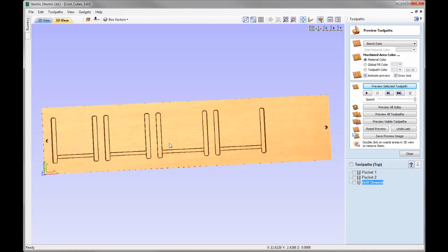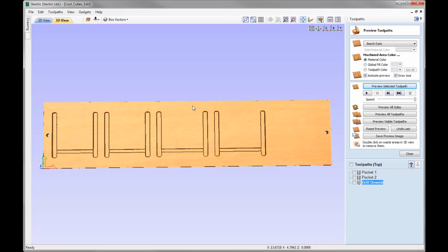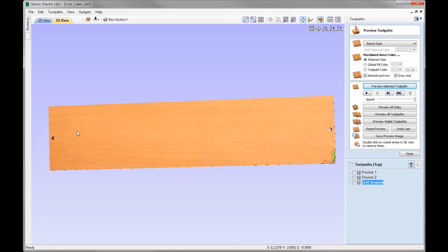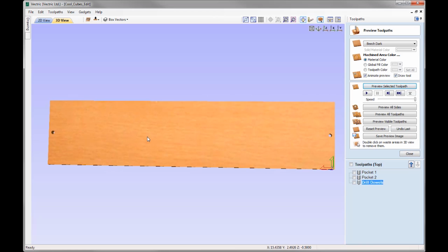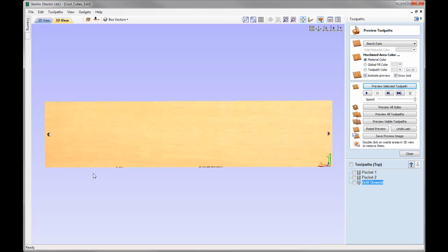At this point, what we'd do in terms of the physical setup is we'd take this material block off of our machine bed, and we'd insert the dowels into the holes that have been drilled into the spoil board, and then we'd take our material and flip that over, and then we'd position that and align it to the dowel holes where we'd secure that in place. And because we've aligned it to the dowel holes, we know that our XY coordinates are going to be aligned with each other. And then we'd look at running the toolpaths for the bottom side.